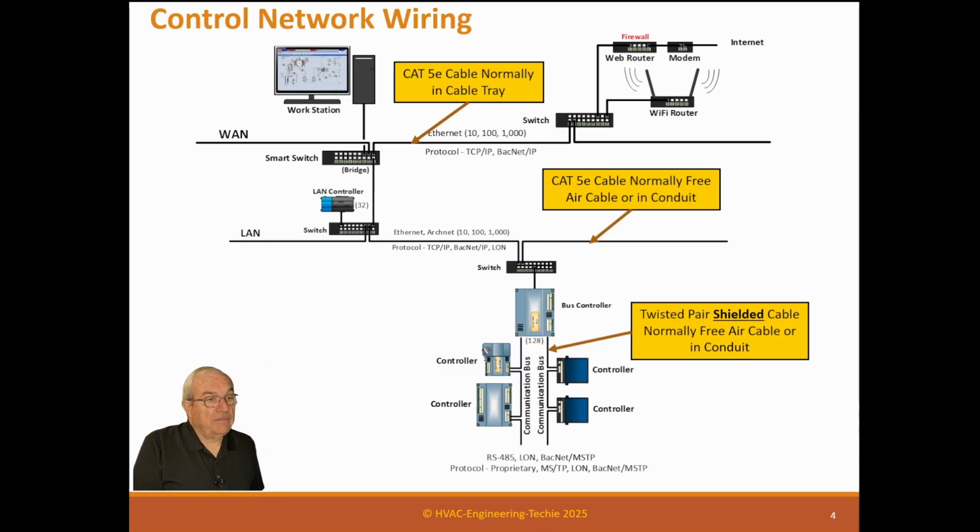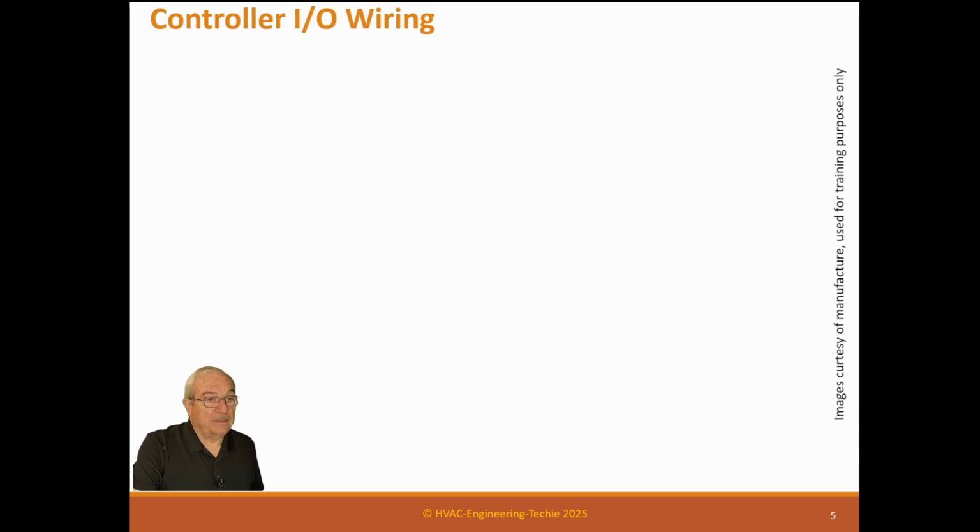Many people buy them pre-configured, in other words, they already have the RJ jacks on the ends of them. But normally, as control contractors, we install the jack. What's really important about how you install those RJ jacks is the wire configuration. You'll have to understand the tip and ring of the wire, and learn how to do that to make sure you always have the correct wire colors on the correct pin of the jack, or else nothing's going to work. Most control contractors carry testers that allow them to plug in the wire to make sure their jacks are good and correctly pinned.